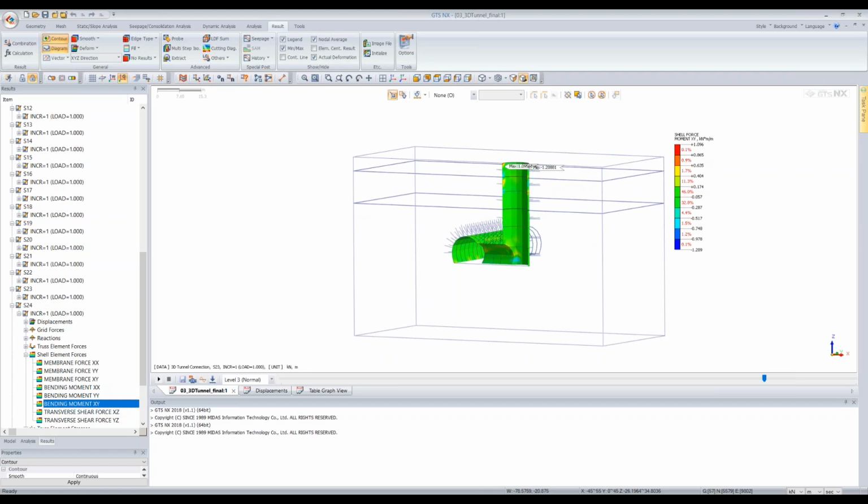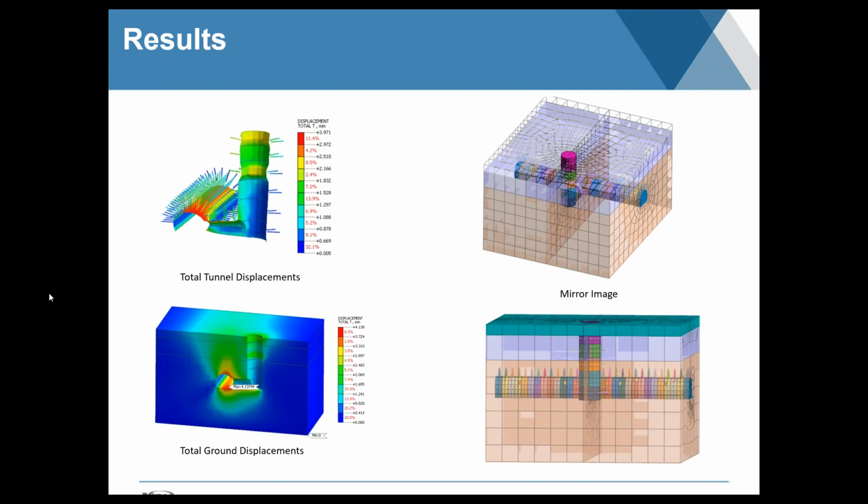So we can now go back to the presentation and start looking at some of the different output methods that we can use for advanced output, especially for construction stage analyses. As I mentioned, in this model, we were only considering the full main tunnel, and for the passage and the vertical shaft, we considered it to be symmetrical, and hence we reduced a lot of the stage time and number of elements by just doing half.